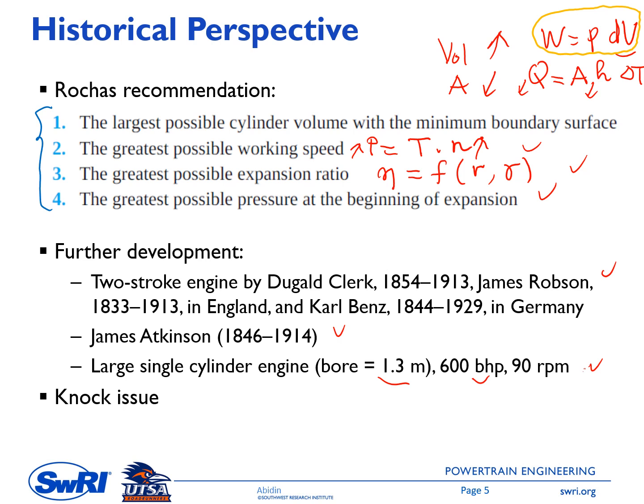With the development of the engine, there was an issue. The issue at the time was what's called knocking. You know what knocking means, right? This is the auto ignition inside the engine when the pressure and temperature are high enough and the fuel can auto ignite. It means it ignites by itself. It doesn't require the external ignition, for example, from the spark plug.